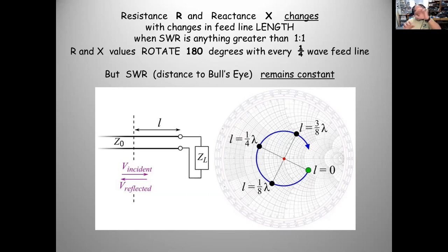The impedances duplicate themselves on a feed line, any feed line. Doesn't matter whether it's ladder line, 450 ohm window line, coax, they all behave the same, but they have different velocity factors. Let me stop here. That's pretty amazing.